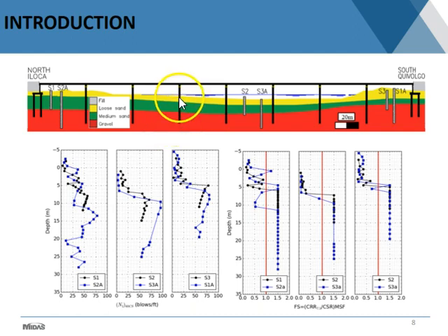The yellow material at the top was the one that is liquefiable. Then you have a medium sand, and then gravel. It didn't have any SPT values or whatever to show that it's susceptible to liquefaction,